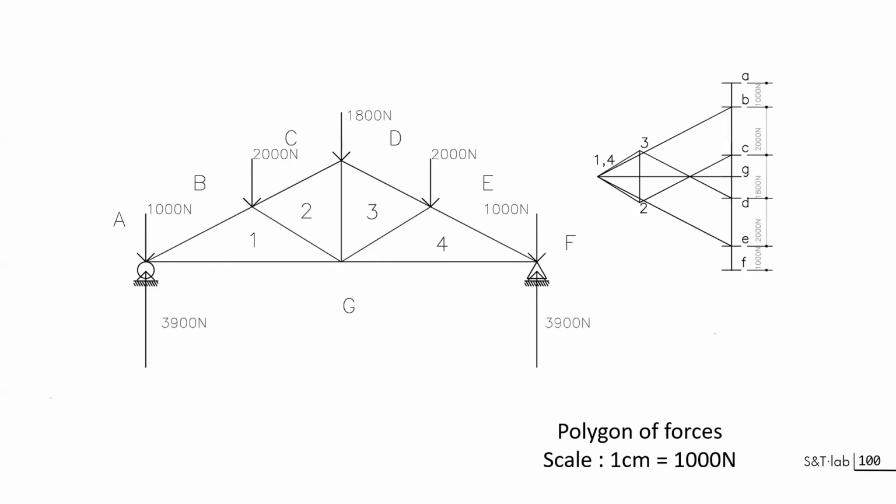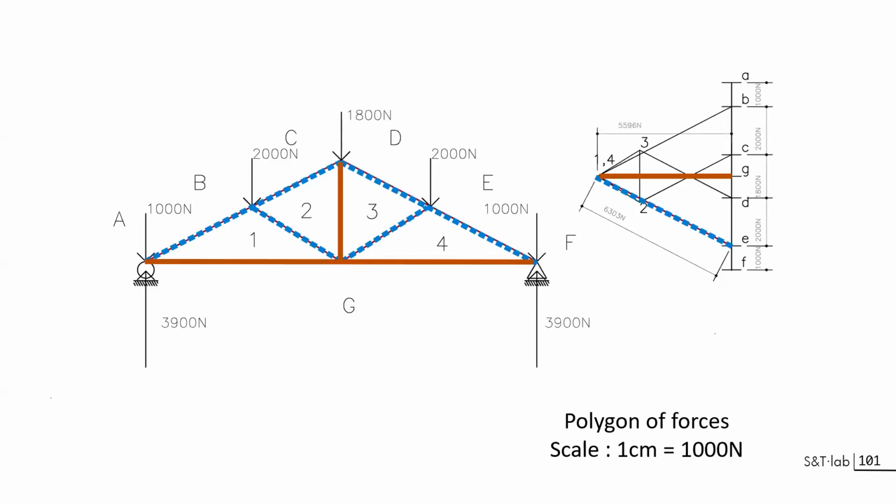I won't detail it, and you can do exactly the same analysis showing which bars are compressed and which bars are stretched in tension. You could say that actually this is easy to guess, what are the forces. For instance, here you have a bar force that is applied in the middle. If you push here, you are not able to sustain the system without this, so we'll have compression on both sides. This compression has to be equilibrated by tension, and here for this force we'll need two bars to equilibrate it. If you are pushing in this direction, we'll need this bar in tension.